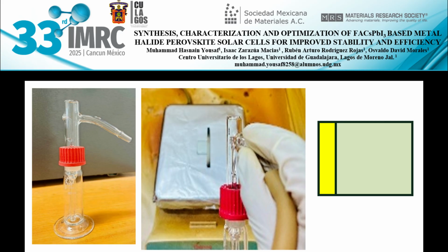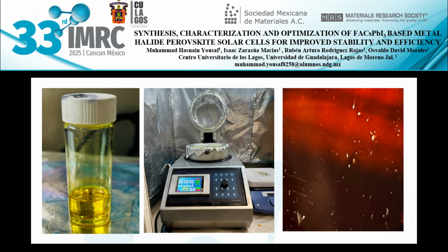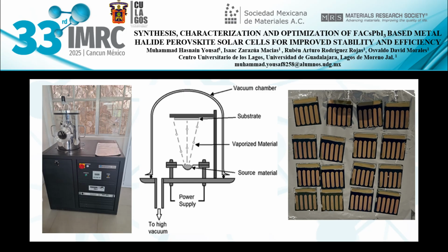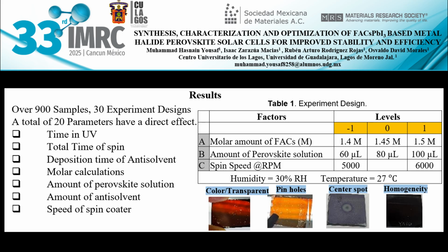The TiO2 compact layer is applied using the spray pyrolysis method. After that, the perovskite solution and spiro-OMeTAD solution are spin coated for the perovskite and hole transport layers. In the end, a metal evaporator is used to deposit the desired counter electrode on the synthesized sample. Moving on towards the results.